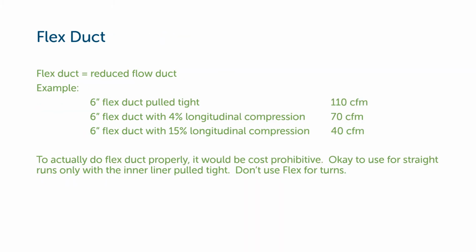Indulge me while I go on a little tear about flex duct. So I think flex duct could be called reduced flow duct. Now, in reality, if you do flex duct properly, it's actually pretty good. It tends to have less duct leakage than standard duct. But to do it properly, I think would be cost prohibitive.